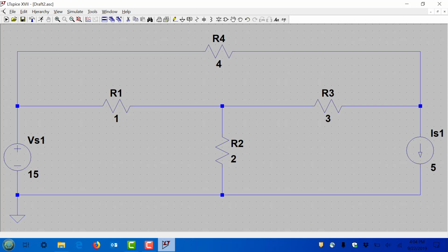Okay, another way you can enter it, it turns out that there's actually a keyboard shortcut. So if I just type the letter R, that's another way you can enter a resistor. So there's 3 ways. Choose one, but after a while, you might find yourself just using the R on the keyboard because it really is quicker. Okay, so that's just some side notes, right?